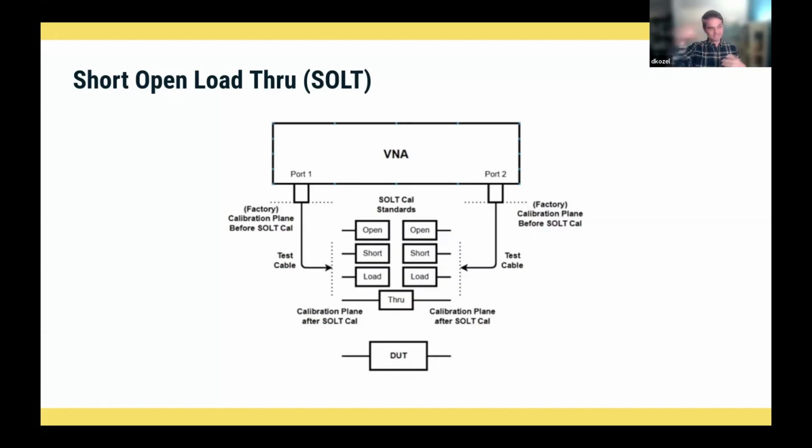What additional term is there if you actually connect a device between 2 of the ports? And so we put a through, what should just be a perfect piece of coax through. That's all of our calibration. Using that, you can solve all the equations.